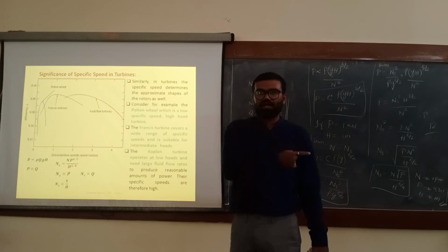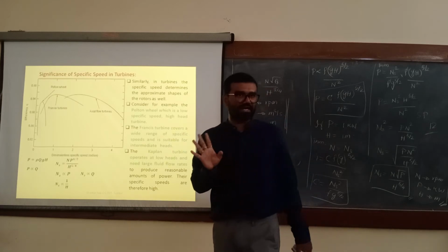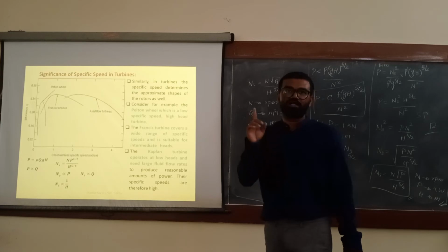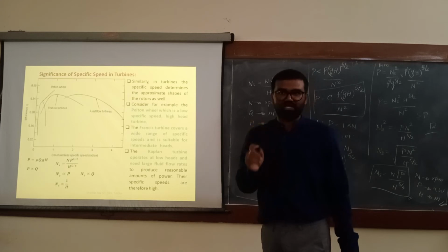That means Jog Falls is the higher head site condition, and Gaganachukki and Barachukki is the lower head site condition. Okay, these are the two conditions. We need to decide which turbine has to be installed. For that, we will calculate the specific speed for the site condition.